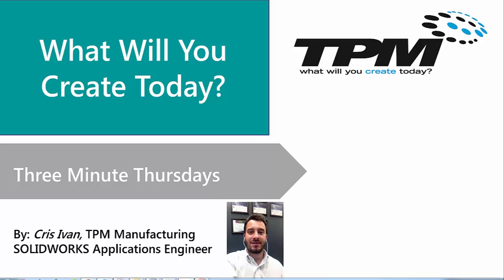My name is Chris Ivan, and today we're going to look at installing SOLIDWORKS by way of an administrative image. To begin with, I'm going to navigate to the folder where I have saved the media from the SOLIDWORKS website. I could also use the provided DVD.